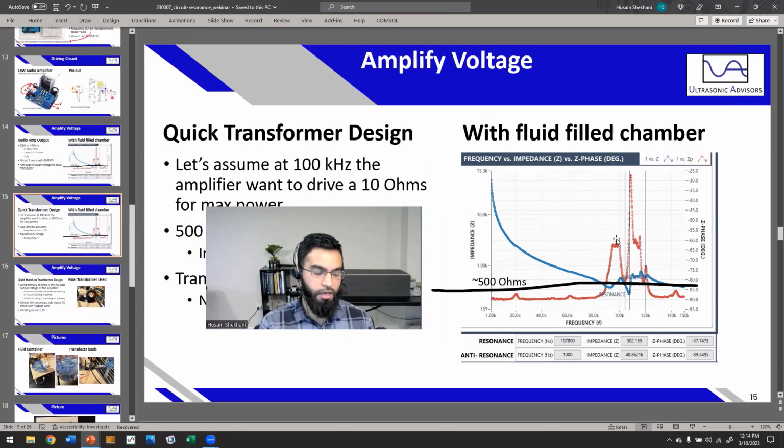You can intentionally exploit that by using an LC resonance. You could put in an inductor, and now you have a resonator, and you don't even have to use a transformer. You may need to protect from back voltage once you turn it off, but otherwise you'd be in good shape, and you could amplify voltage that way. But this is the most straightforward circuit, the one that took the least amount of tinkering around.